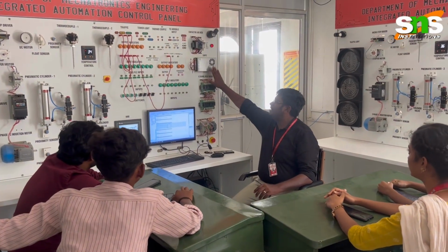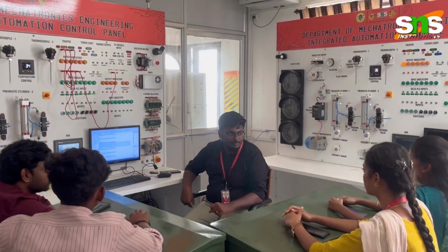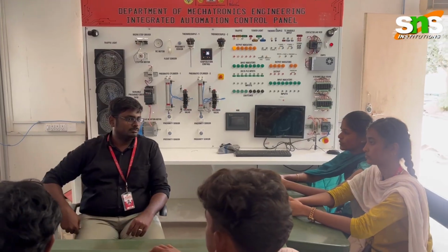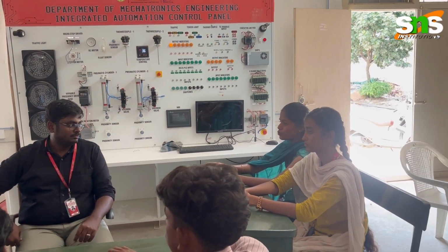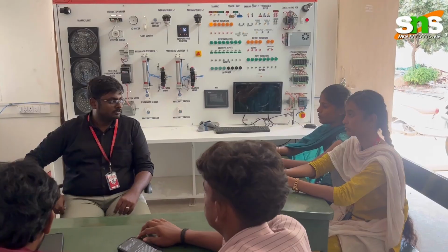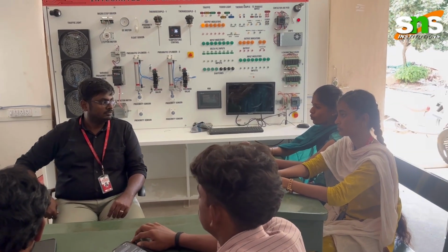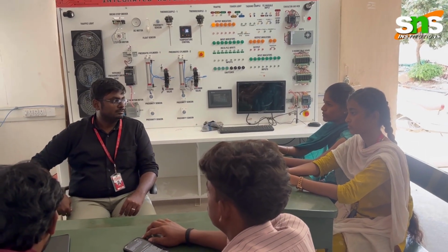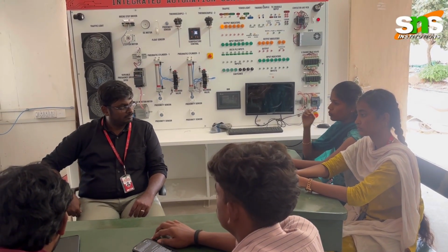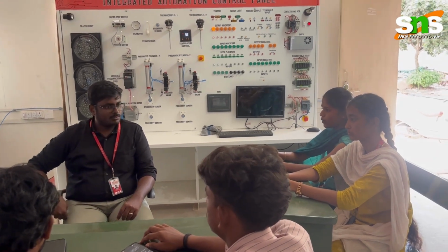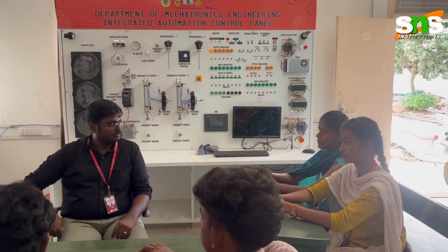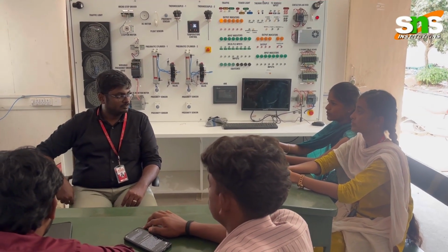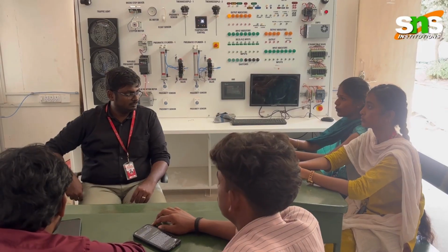The next major component is SMPS. Can anyone explain about it? SMPS in PLC stands for switch mode power supply. The electrical power supply is used in the PLC to convert electrical power from one form to another. The role of SMPS in a PLC is to convert the AC mains 230 volt or 110 volt into low power DC voltage of 24 volt. It is a stable and regulated power supply for the PLC components like sensors, actuators, input and output, and the CPU module.